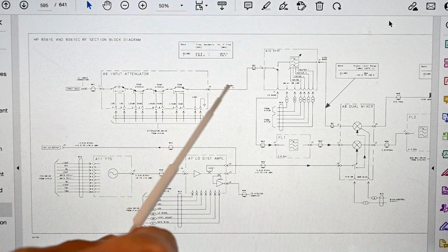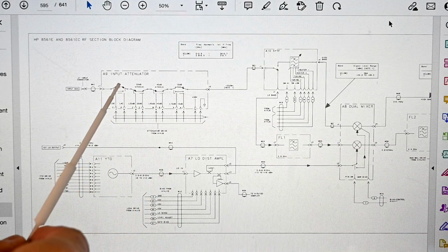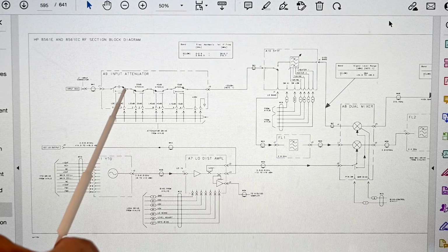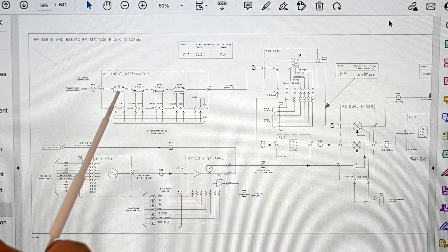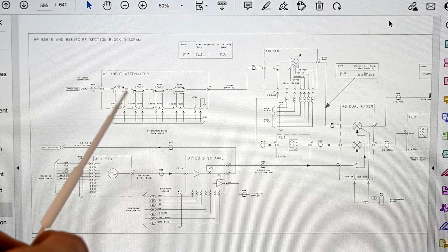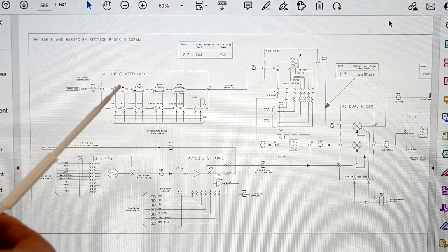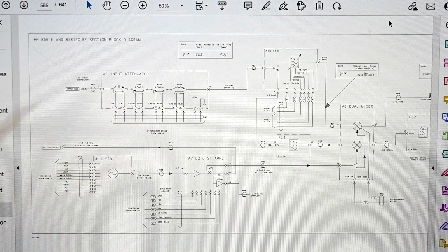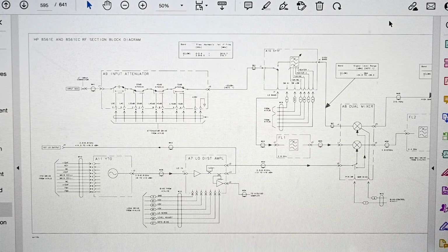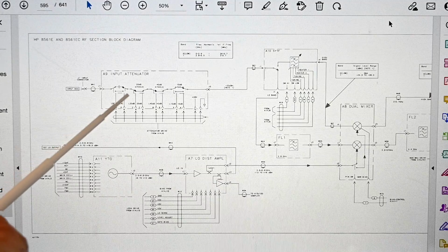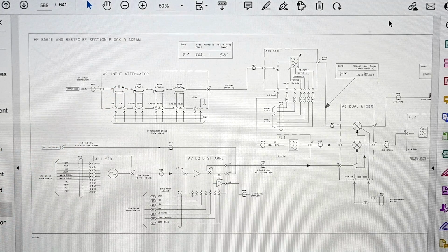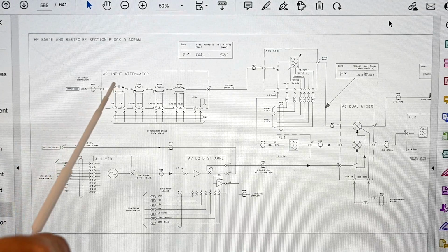So stepping back over to this point, this is the A9 input attenuator. If we look inside here, the RF input comes over, there's a capacitor, and that can be switched for direct coupling or AC coupling. It defaults to AC coupling, which is the safest, because with DC, it's spec'd at 0 volts, but I think about 0.2 volts or higher is a damage point. So basically no DC voltage allowed, but with the coupling capacitor, I believe up to 50 volts is tolerable, because it will block that.